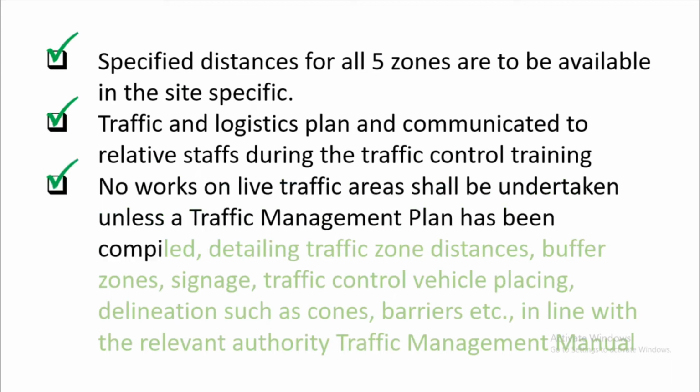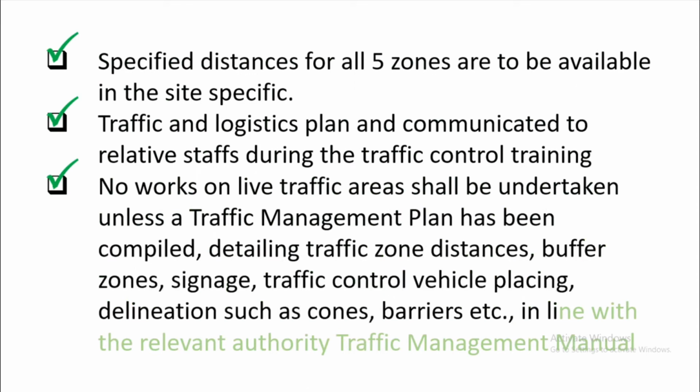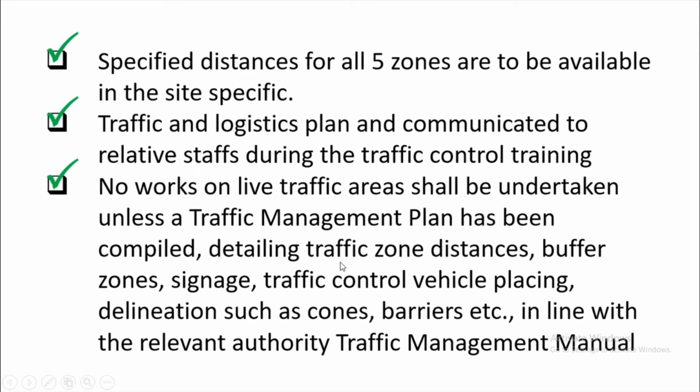No works on live traffic areas shall be undertaken unless the traffic management plan has been compiled, detailing traffic zones distances, buffer zones, signages, traffic controls, vehicle placing, delineations such as cones, barriers, etc., in line with the relevant authority traffic management manual. So we need to make sure that before we start the job, traffic management plan is prepared in compliance or in line with the traffic management manual from the local authority.